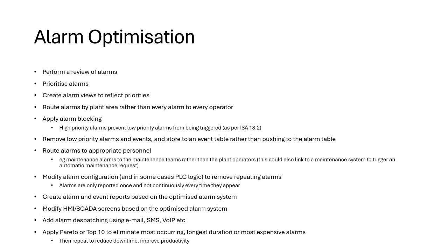So a big topic is alarm optimization. It's common when designing a system to generate alarms for every single thing that can go wrong. That's a great idea because you want to have some notification that the operations aren't performing as they need to. But what can happen is, over time, people add more and more alarms because there are problems that need to be tracked. And what can happen is the operators can be overwhelmed with too many alarms.